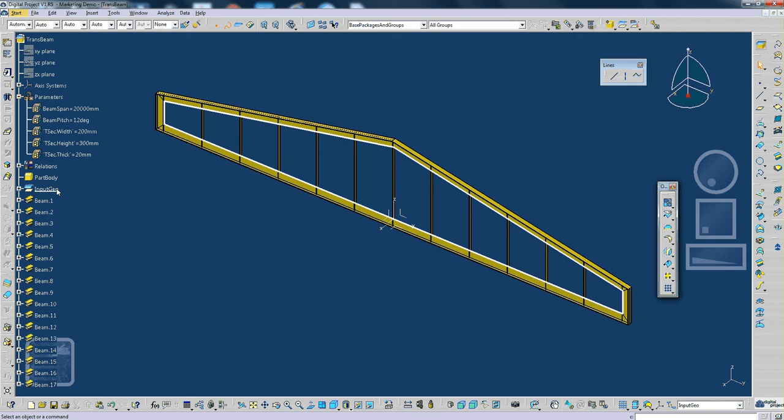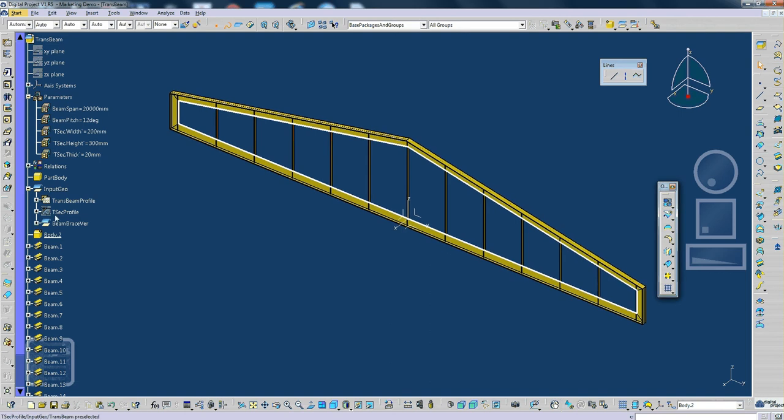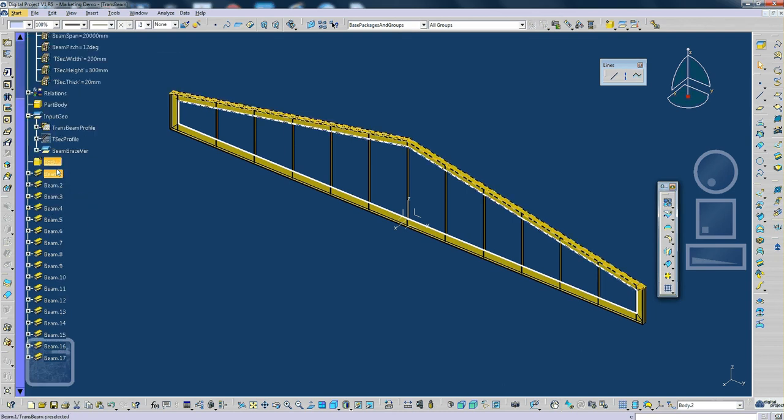So from here, I will add. Oh, not geometry set. Sorry, add solid. Okay. The reason why I can select it is because I still have the selection filter on. Remember, so I have to turn this one off. Look, turn this off, turn this off. Now I can select. Yeah. So pick this and then I click pad.